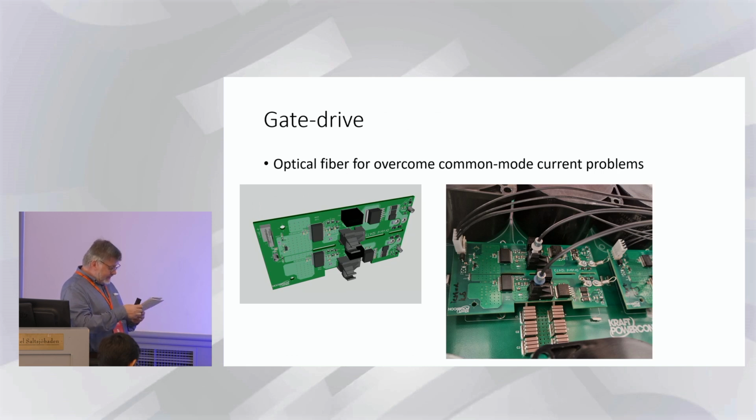Little bit about gate drivers. As everyone knows, the transistors need to have gate drivers. And we started with plug-and-play gate drivers, intelligent gate drivers with processors on the low voltage side, but we had severe problems with common mode voltages.